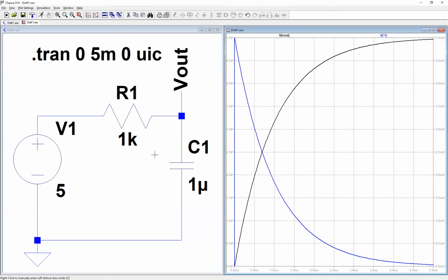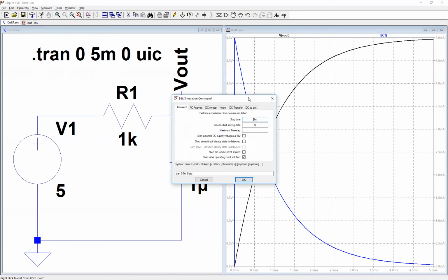Okay, one last thing that I want to show you, I think probably the last, is that there is one parameter when you do a transient simulation that you have to set up, which is the time step. We did not do it before. You can access that one here. So before, remember to click here. This window has to be selected because we want to work here. You can right click here. Okay, automatically the window will appear.